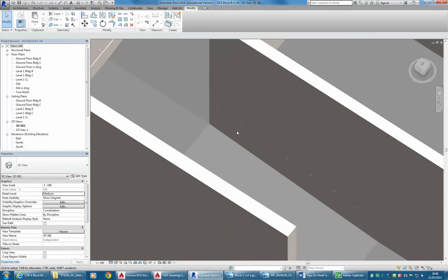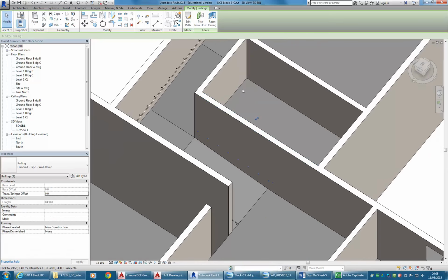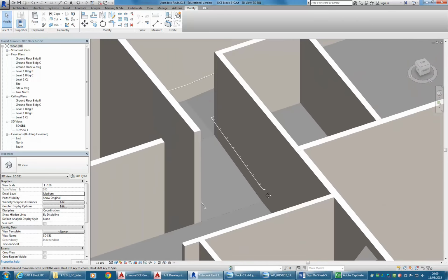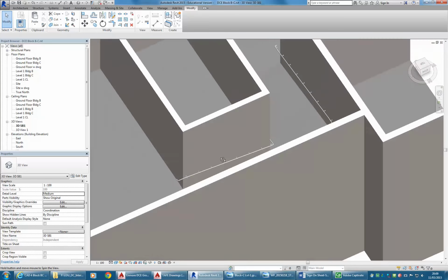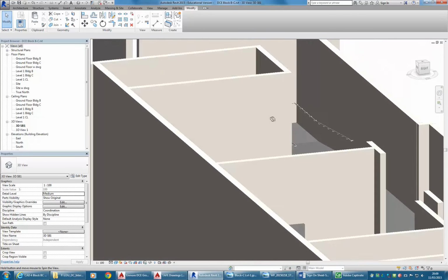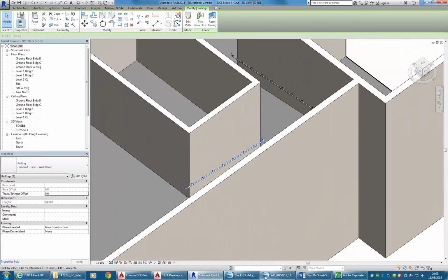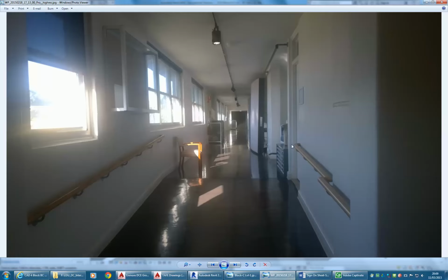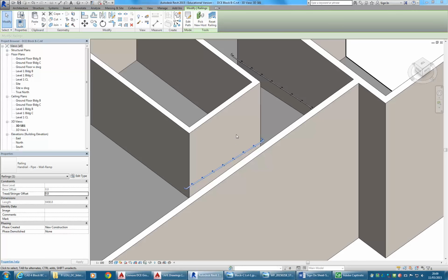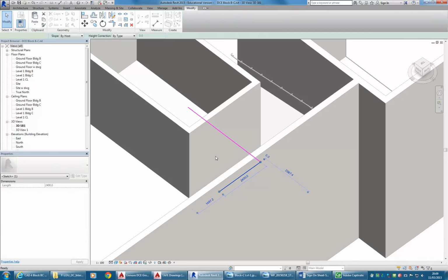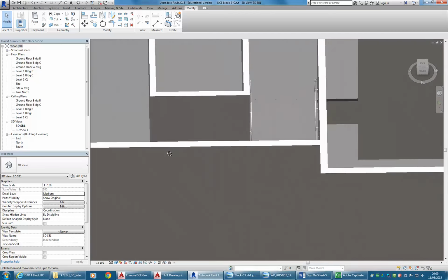And so again, with this inner railing, I need to do the same thing. Just because it's L-shaped, the arrow's gone to one side. And okay, so we'd need to do some work to change what happens at the end there at some point, but that's easily good enough to get started with that railing. And well, we know that there's a door actually there, so the railing would stop there, and so I can simply just go to edit path, and probably by eye at this stage drag that back a little way, tick to finish, and that again will be plenty for now.